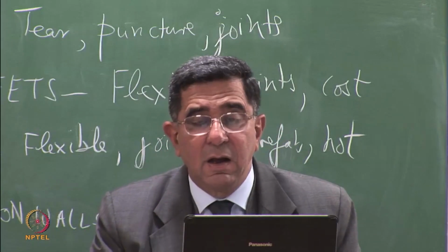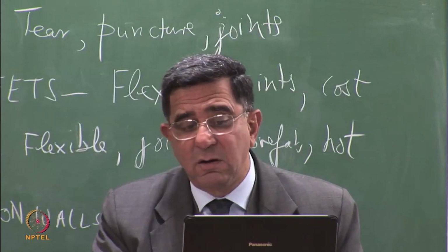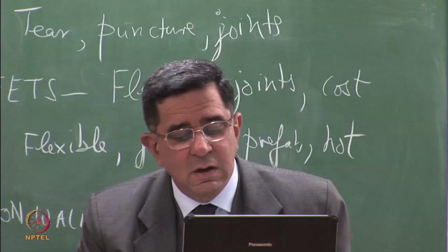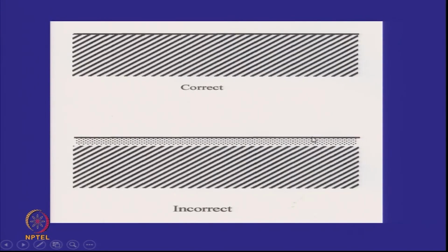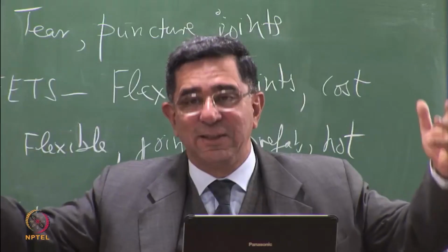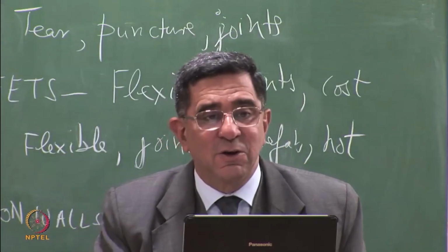And remember, many people install this wrong. This is correct: you have clay at the bottom and geomembrane at the top. If you don't have intimate contact, please understand what's happening. Suppose you have sand in between or you have an air gap. What happens? You have a hole here, the whole thing becomes filled with water. If the whole thing becomes filled with water, you again have water over a large area and the entire clay will seep.